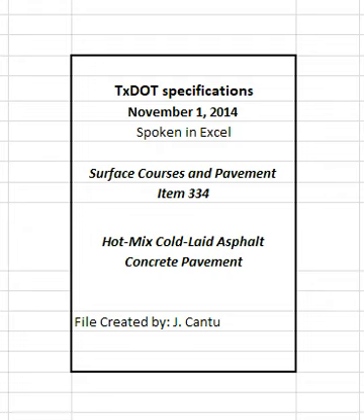4.2.2 Storage and heating of asphalt materials. Provide enough asphalt material storage capacity to meet the requirements of the plant. Do not heat the asphalt binder above the temperatures specified in item 300, asphalts, oils, and emulsions, or outside the manufacturer's recommended values. Keep all equipment used in the storage and handling of asphalt material clean at all times and operate the equipment in a manner that will prevent contamination with foreign matter.